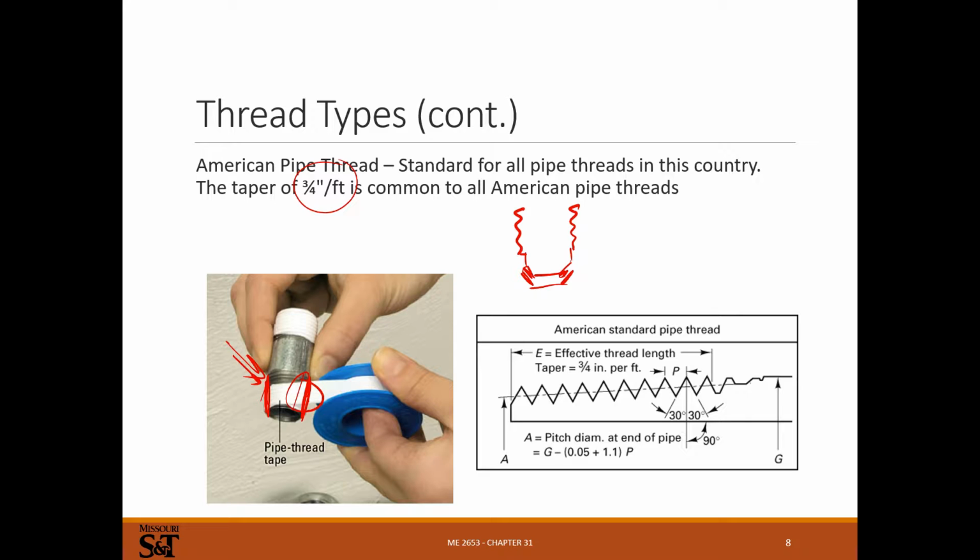There's O-ring seals too, where you'd have straight threads in an O-ring seal, and those wouldn't require a lot of torque. But the main reason they use these on pipes, like in plumbing applications, is they're cheap. They're easy to do in the field.